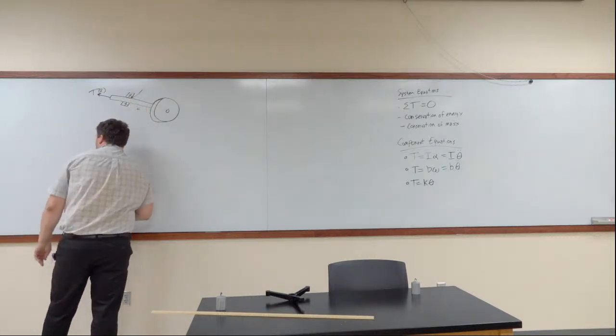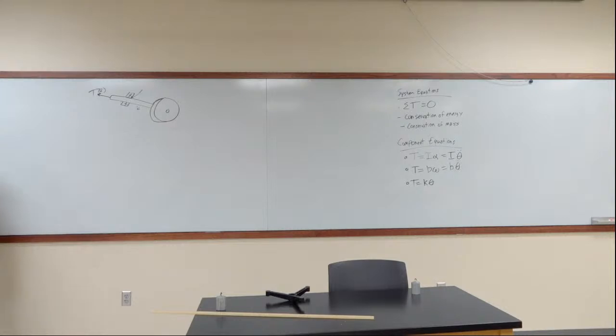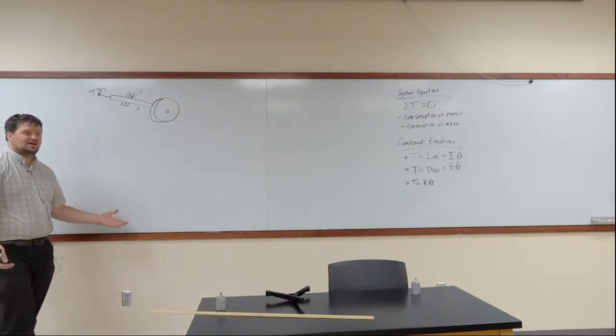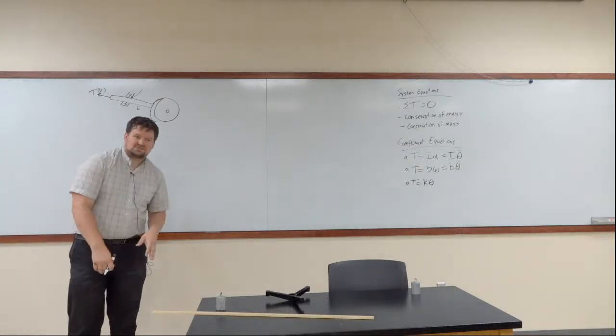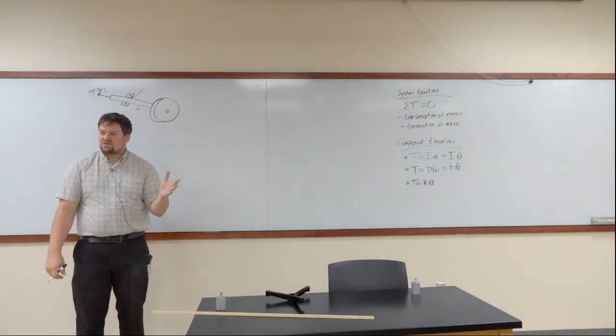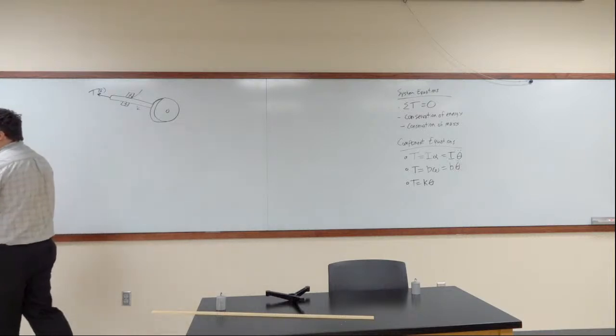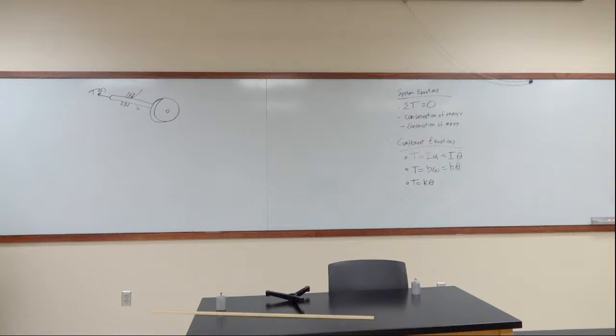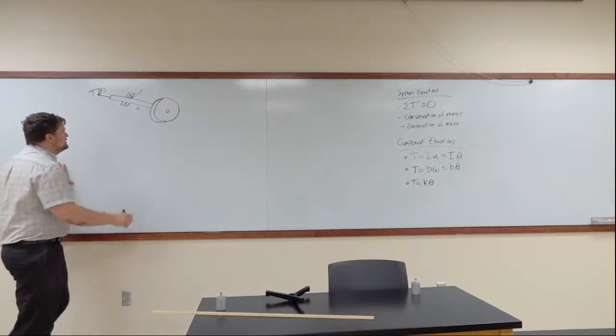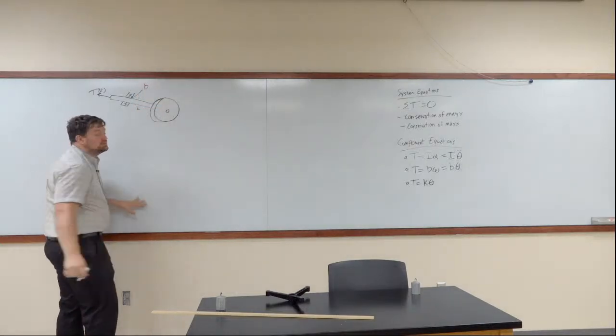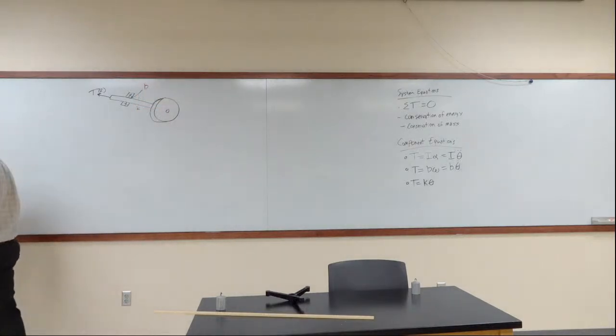Now, we have a bearing. Anytime you have a bearing, there's going to be a small amount of frictional losses. That's something you can't help. The frictional losses are associated with the speed of the shaft. What does that mean? It means if the shaft is not moving, you have no frictional losses. You're not losing energy. Only when the shaft starts to move do you have frictional losses. The faster your shaft moves, the more frictional losses you have. This has a coefficient B.